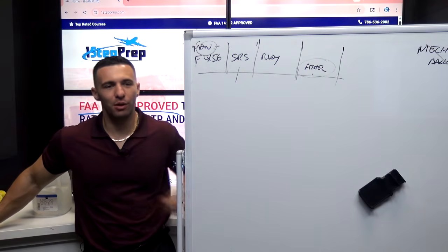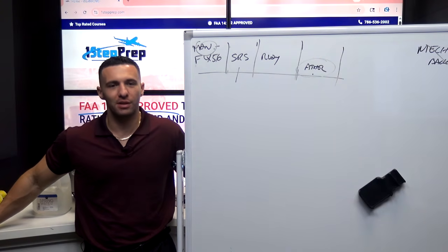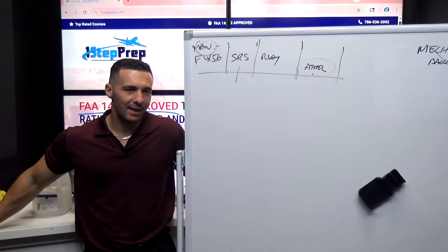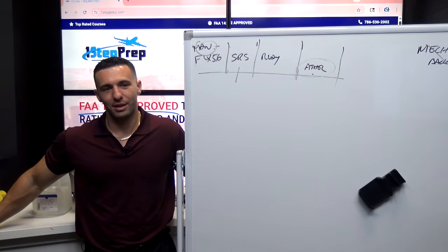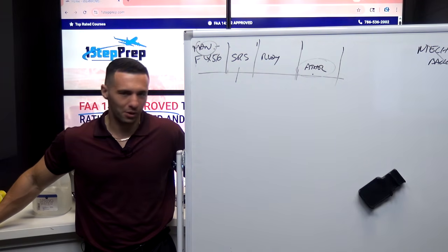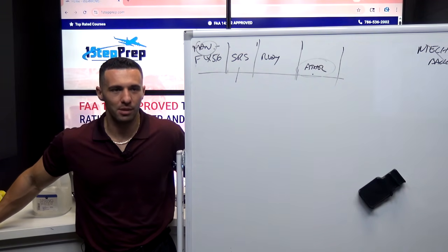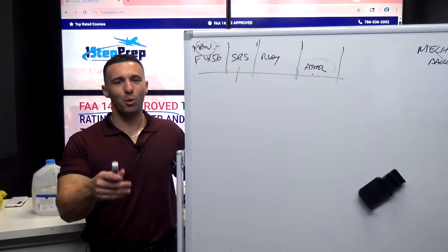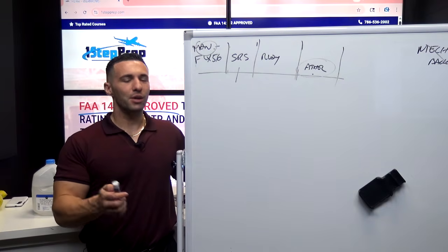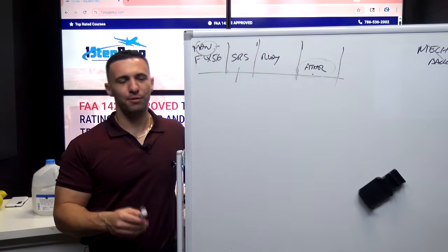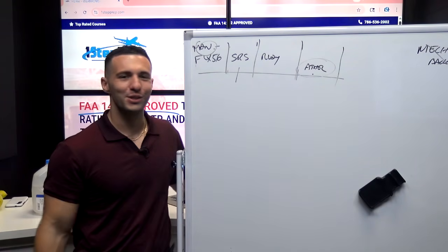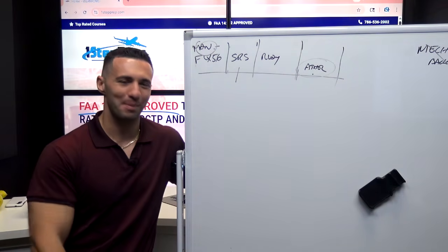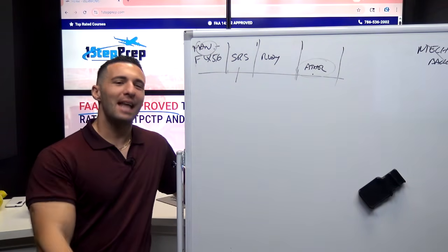Yeah, no. Okay, so you can put the gear down first and delay the autopilot disconnection, and then at the last minute, you can go ahead and disconnect the autopilot, and it'll still go to direct law, no problem. Just be ready for it, it's going to be sensitive. Less is more on the side stick. You can literally fly this with your fingertips. I mean, if you find yourself doing all kinds of input, you're working too hard, brother and sister. You've got to let go of the stick, man.